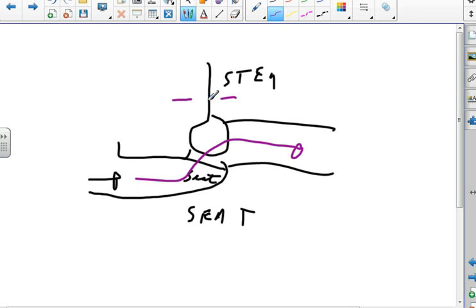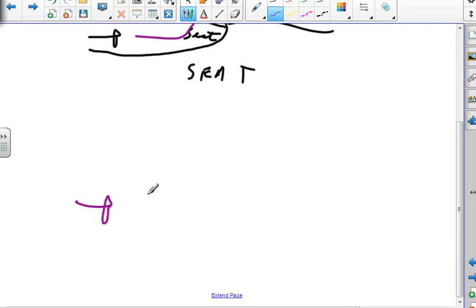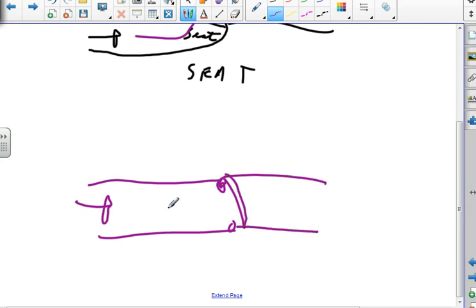So we have globe valves, seated valves, choke valves, ball valves. Okay, what's a check valve? Pressure? Only going to allow flow in one direction. Yeah, so a check valve's only going to go one way. So if I'm supposed to have flow that way, then I got a valve that there's my C, and then there's my thing there. Now I can swing up and I can flow that way, but if I get flow this way, it's going to stop it. So I'm going to stop the flow that way. So that'd be a check valve.